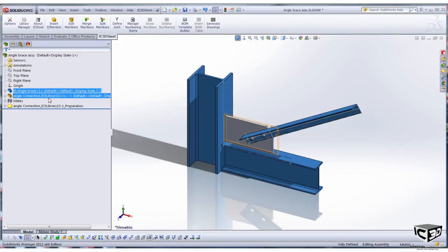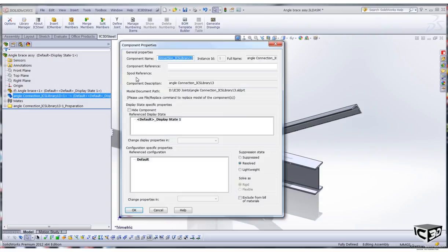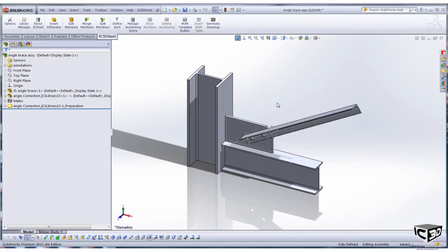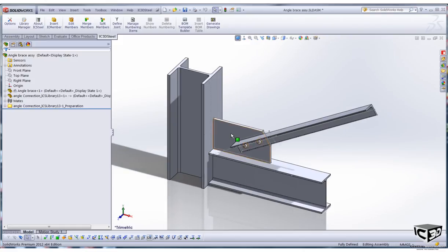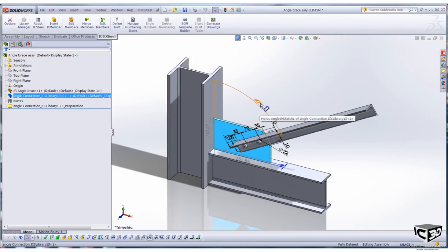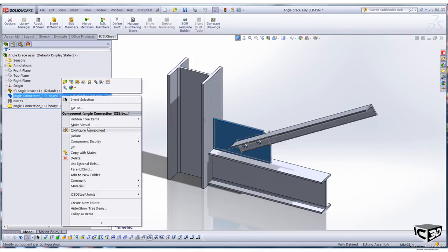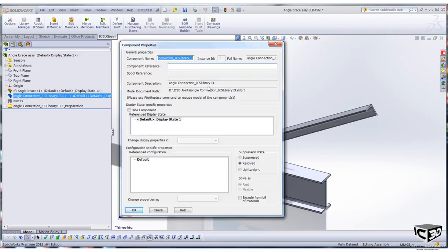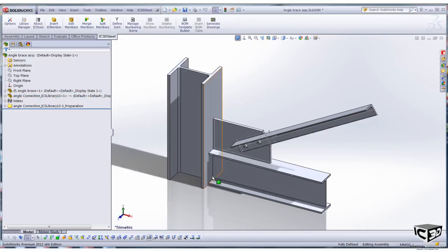In this case my component reference, for example, is blank, so generally you would type something in here as well. The same goes for the custom properties, where I might want to have a specific property. For example, in this case I want these 60 degrees to be deployed in my custom properties, but also back into my component reference in here. So the way we do that is we can control that with a post script.